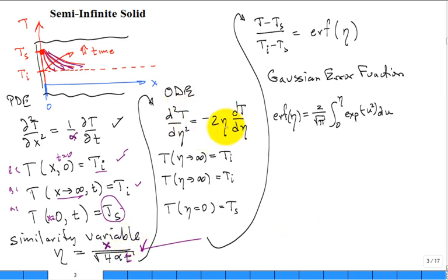Well, there's some math. You transform it into an ordinary differential equation. You have two space derivatives with respect to eta and one space derivative with respect to eta. This eta times dT d eta makes it a little more challenging. Our boundary conditions transform. Notice that this one and this one give us the same, like 3 have to collapse into 2. So the initial and boundary condition can collapse into the same condition for the transformed problem in the ODE space. So this is like the first and this is the second. Well, that's a well-posed mathematical problem. It's your old friend.